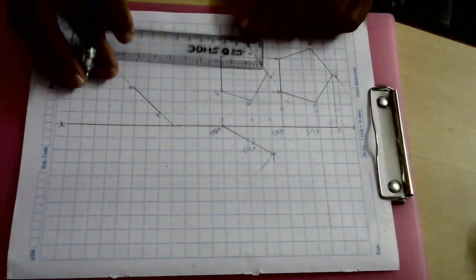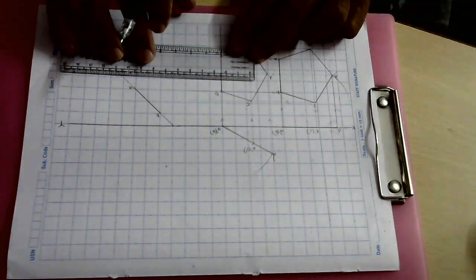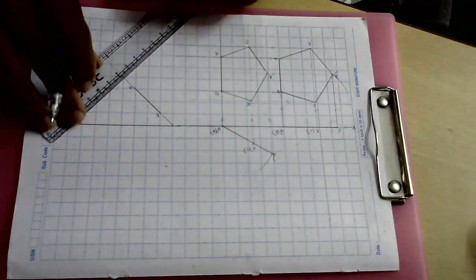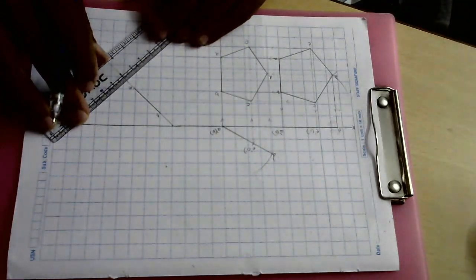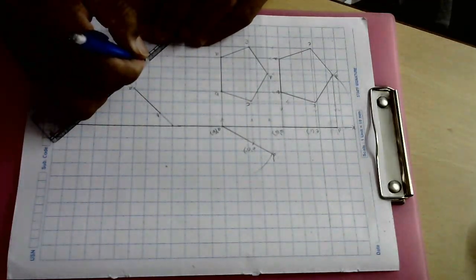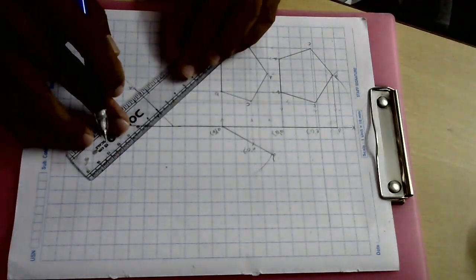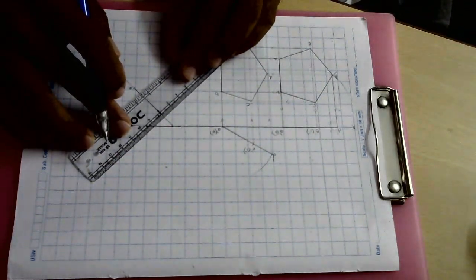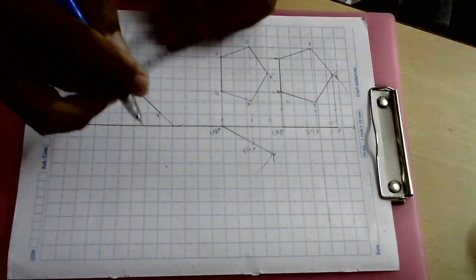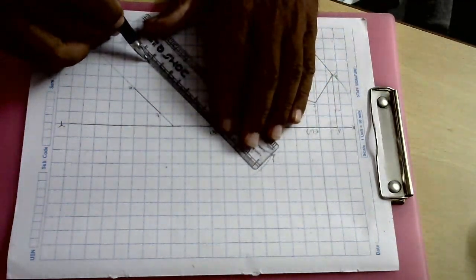Now measure the parallel distance of these two construction lines. So it is about 24 mm. Okay, so now keeping your scale in a perpendicular direction, measure the distance of 24 mm. Let us mark one point over here. Again measure the distance, ten, 20, 24 mm here. Let us mark one point. So now join these two points with a very thin line.